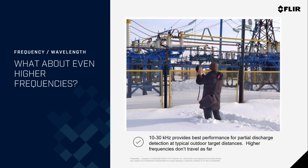Something to keep in mind is that when your system goes to higher frequencies, it not only provides no benefit to you, it actually results in reduced performance because the dynamic range of the microphone digital signal is spread across a broader range of frequencies.